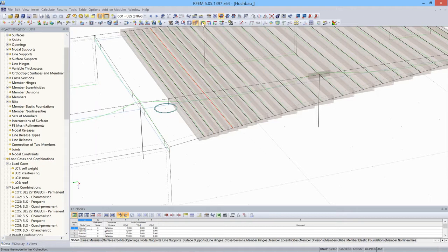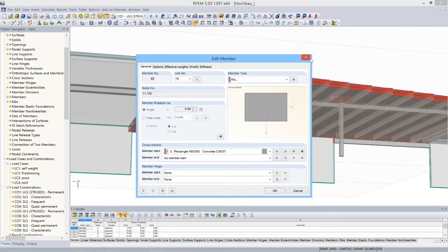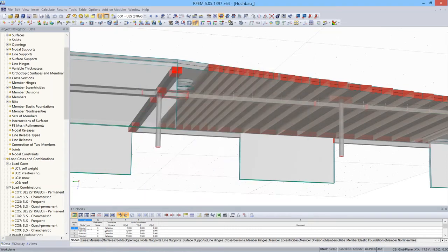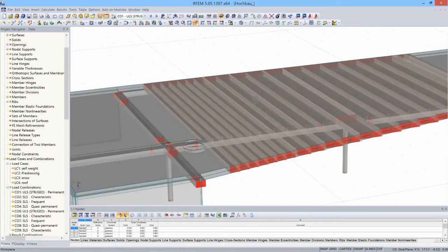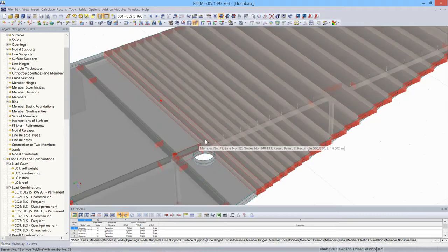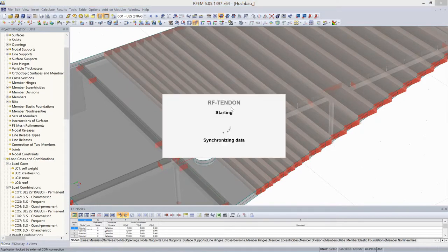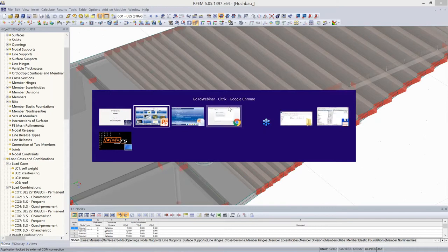The last one which I want to show is this beam and slab system. You can see here that I have a rib which is linked to the slab, and RFEM can integrate internal forces from a defined width of the slab together with the rib, and we can get the T-section, which then is used in the analysis and in the design.